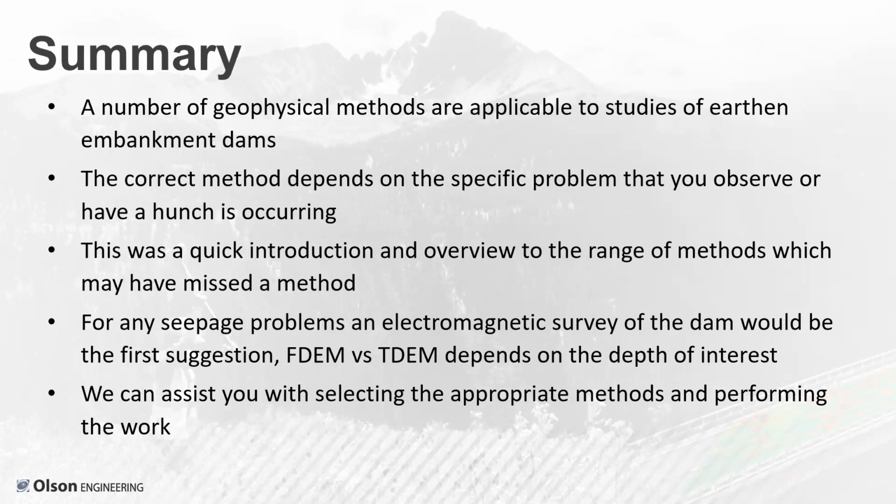If you're worried about scour or slumping or other large scale issues like that, then a combination of GPS or GNSS or InSAR, other methods like that, or even flying over and doing photogrammetry, which I didn't mention in this presentation. There are other methods that can be used to assess those reasonably quickly.